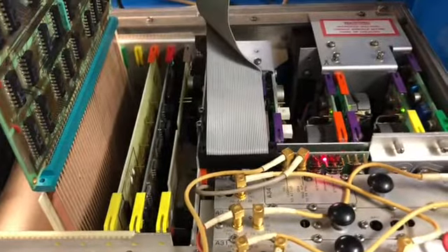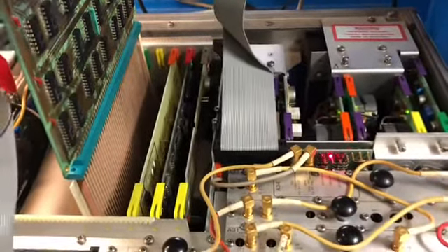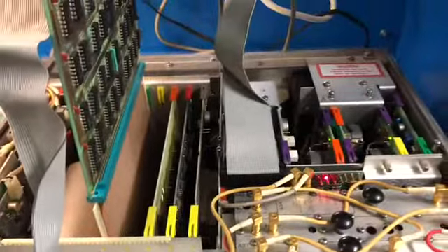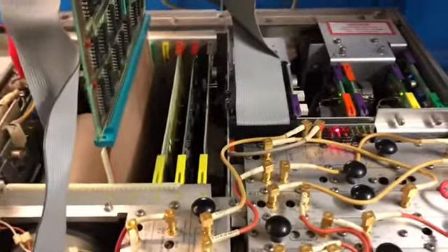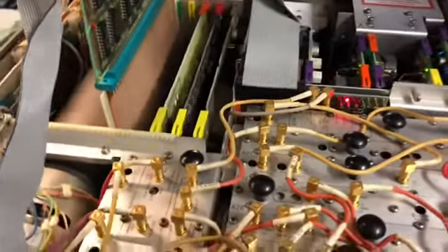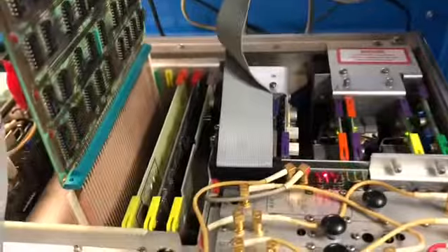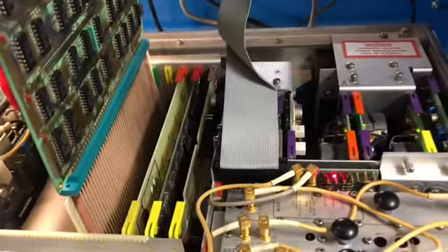But with troubleshooting, I found that the address codes in the RAM are wrong, but the input addresses are fine. So it's something that is coming out from the RAM board. I have tried to remove the RAM board to see if it's loading, but it doesn't make any change.